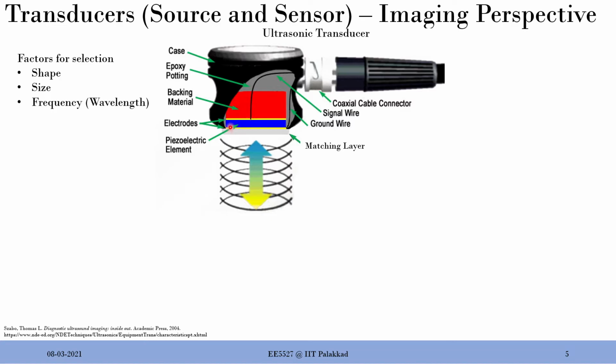So you do have a piezoelectric material surrounded by 2 electrodes, and one electrode is going to the signal and the other one is going to the ground. So a high voltage will be applied across this, and that voltage is decided by who? We will be deciding, the waveform will be deciding that voltage and the shape of it, or the pattern of it, how you want to excite these electrodes. So that is coming from here, right? That is your digital system sitting somewhere here, and that is giving this signal here, and that signal is applied across the piezoelectric material between the electrodes.